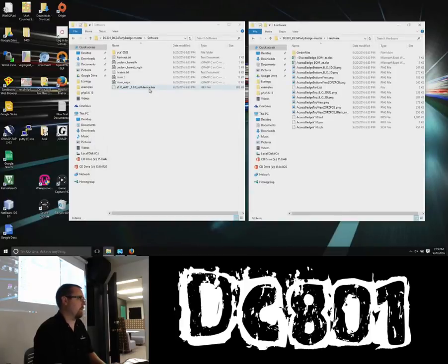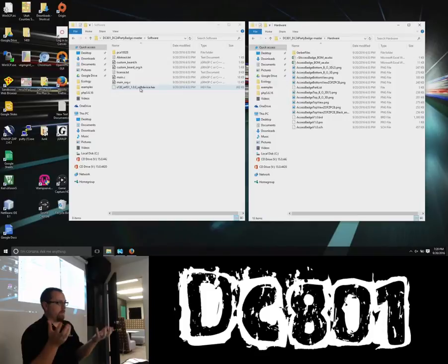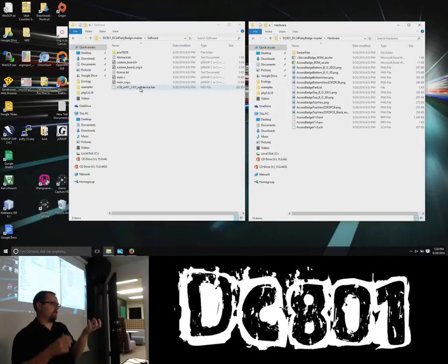So within that GitHub, we include the S130 nRF51 version 1 soft device hex. This right here will let you become a central and a peripheral device at the same time. We don't have a central made for our chip right now, but a central will let you connect other peripherals to it and then broadcast it through so you can do mesh networking. That will be a possibility with the BLEs, especially the newer BLEs that do Bluetooth 4.2.